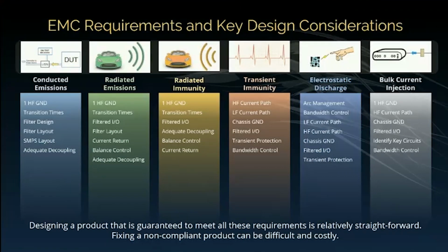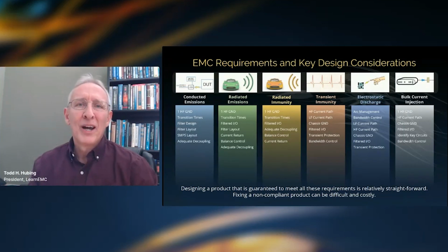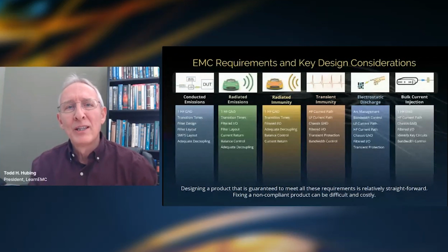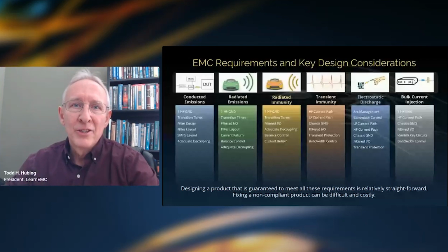Whereas with other companies that I have worked with in the past, they largely design it to work, and then they take it into the EMC lab, and then they start thinking about what they need to do to be compliant with the EMC requirements. And that generally is not a very good approach, because if you do that, your options for fixing your product and meeting the requirements become very limited. They become more costly, and your schedule is going to slip.